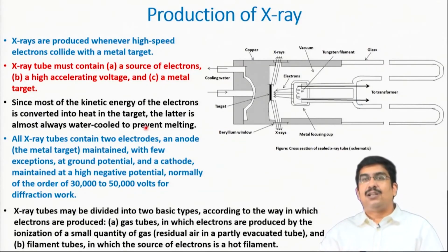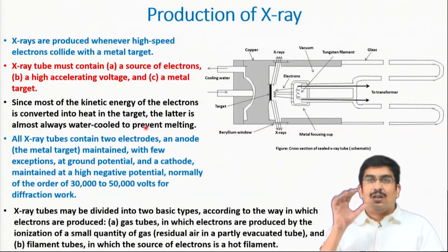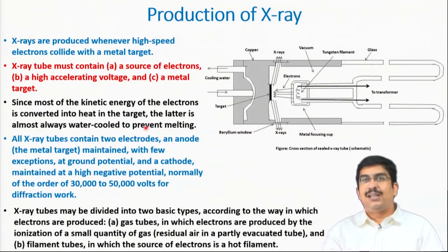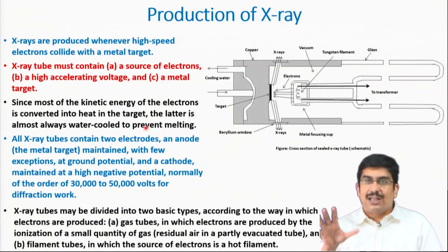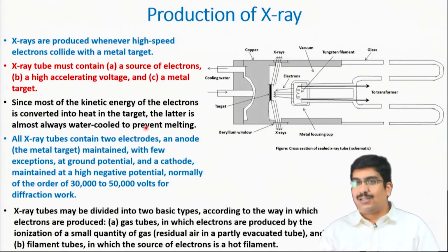The intensity of the continuous X-ray spectrum that these heavy elements give is much higher. We already discussed that. Even the characteristic X-ray spectrum that they can give is pretty high in energy, and the intensity is very high. So most often, at least for continuous spectrum where the white radiation is needed, we generally tend to see tungsten or moly as a metal target.